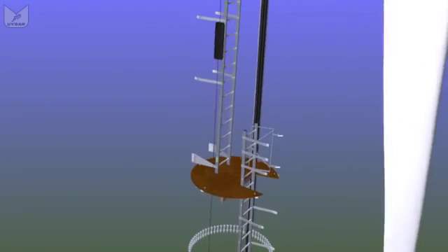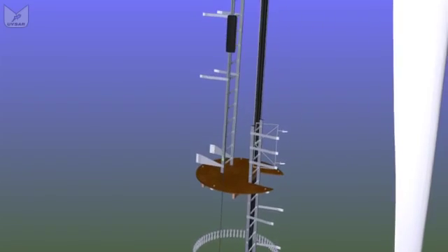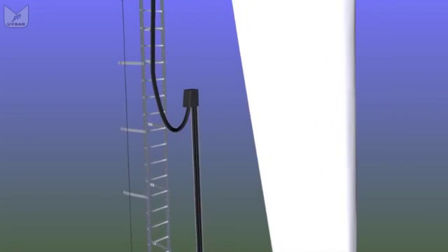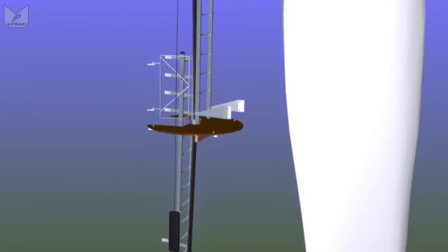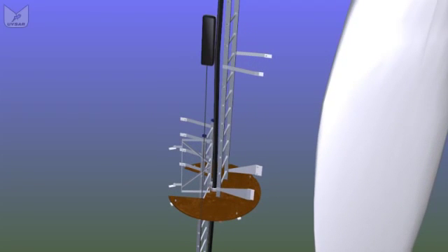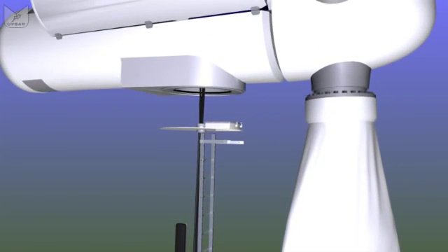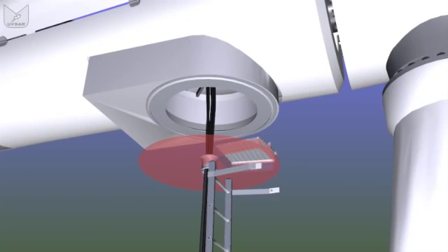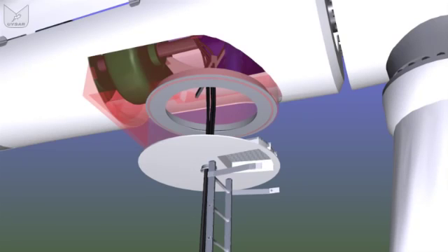But eventually the main cables stop being attached to the wall and they hang freely in the center of the tower, so they can twist as the nacelle rotates to face the wind. If they twist too many times, the nacelle will spin itself around to remove the twists. But as we move up, now the cable goes through a hole in the center of each platform, and at the top of the tower we have a steel platform with a sealed trapdoor, which we call the yaw platform. Just above that we have the yaw ring with the bearings that allow the nacelle and the rotors to rotate around to face the wind.